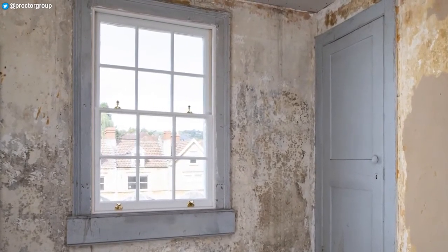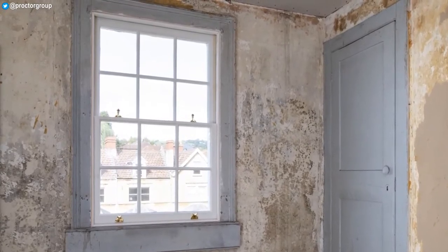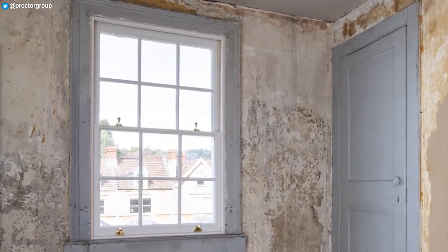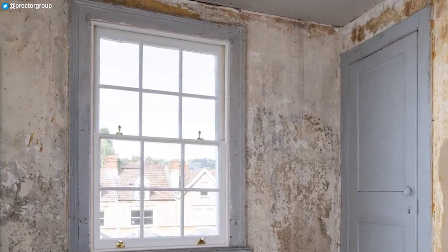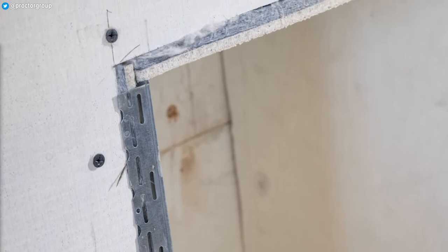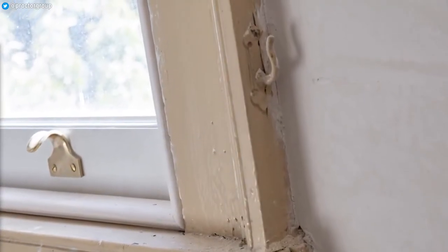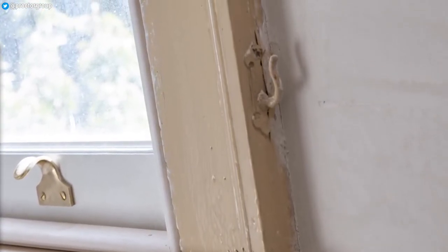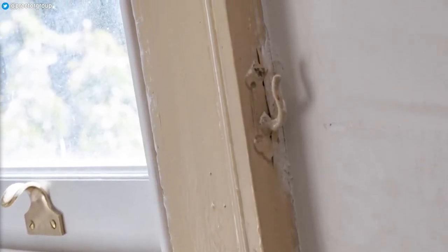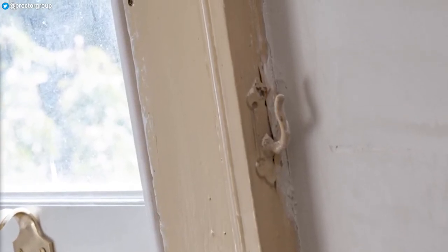Property owner Mike Moore obtained planning permission to insulate the top floor of this Grade 2 listed Georgian townhouse, as it is single skin 6-inch Bath stone and very heat inefficient. All walls have the original lime render and skim, so they need to breathe. The property in Bath was built in 1818 and has been in his family for 101 years since 1919, so it needs some serious upgrading. The project was initially specified utilising 100mm of conventional insulation, necessitating moving door frames and rebuilding window reveals, as well as a fair amount of lost floor space.